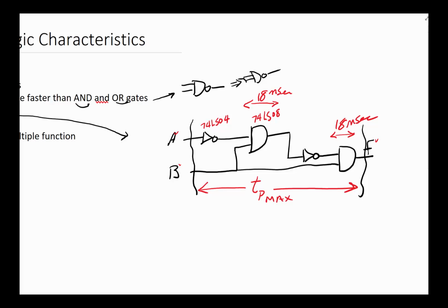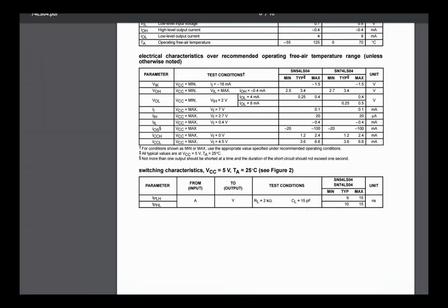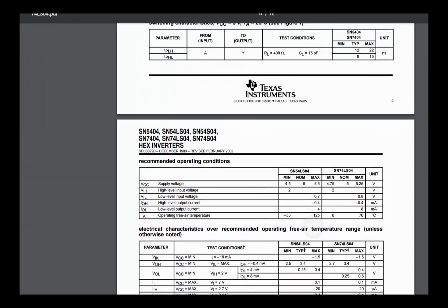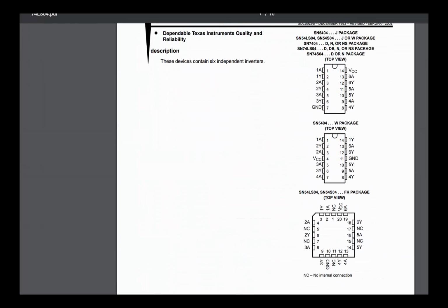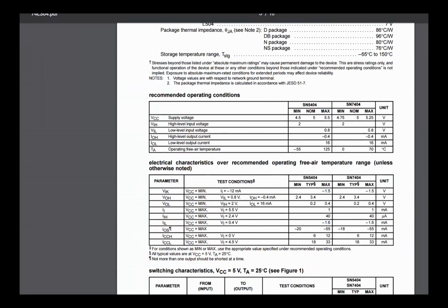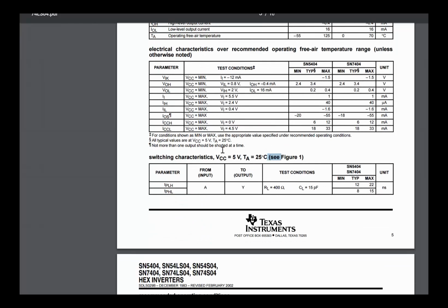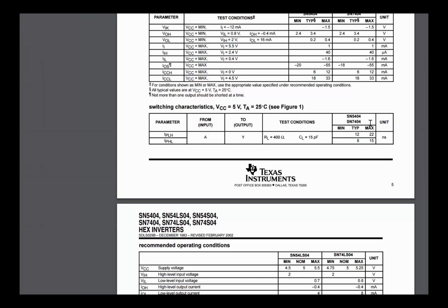So let's go ahead and go back and figure out if we can find what the 74LS04 delay is. So we're going to go back online and look at the data sheet, which is the 74LS data sheet. As you can see, we've had to go quite a ways down the list before we found it. So the first page was basically how the package is set up, second page ordering information, how it's connected, how the internal is done, and then eventually we get to a place right here where we see the timing, the propagation delay. Since we went with the high loading, and this one doesn't have high loading, if you're going to load it higher, we have to degrade this ourselves.